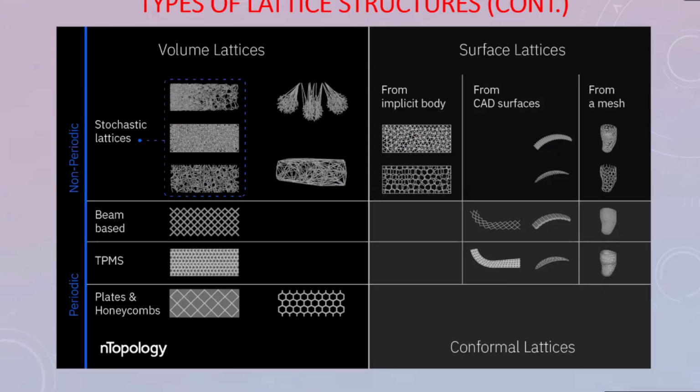For a hybrid lattice structure, I will suggest you have two different STL files, where you need to have two different lattice structures which you need to incorporate. Select the first STL file, then select a particular lattice that will be implemented. For the second STL file, you select it and select the next lattice unit cell. Then you can have this hybrid lattice structure with the two different STLs. Then you can combine the two STL files into a single STL file using software tools available in Magics.